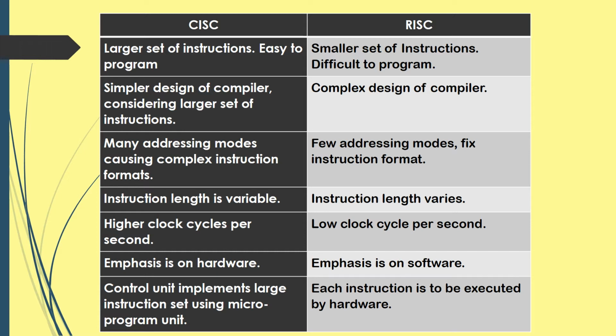Here it is reduced. In CISC, memory to memory, load and store are incorporated in instructions. In RISC, register to register, load and store are independent instructions. In case of CISC, high cycles per instruction, small code sizes. In case of RISC, low cycles per instruction, large code sizes. In case of CISC, transistors are used for storing complex instructions. And in case of RISC, it spends more transistors on memory registers.